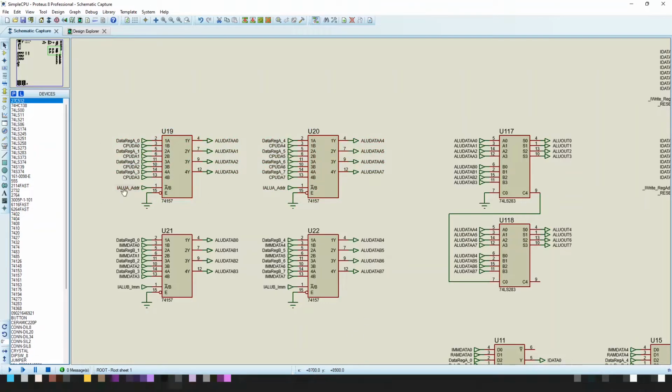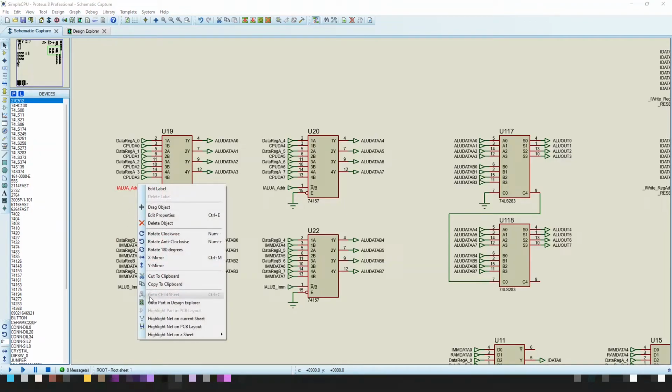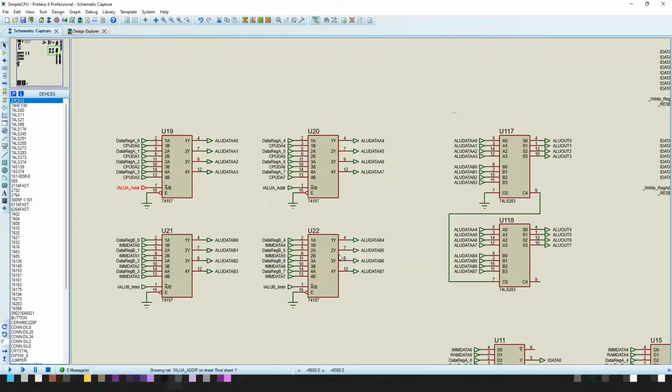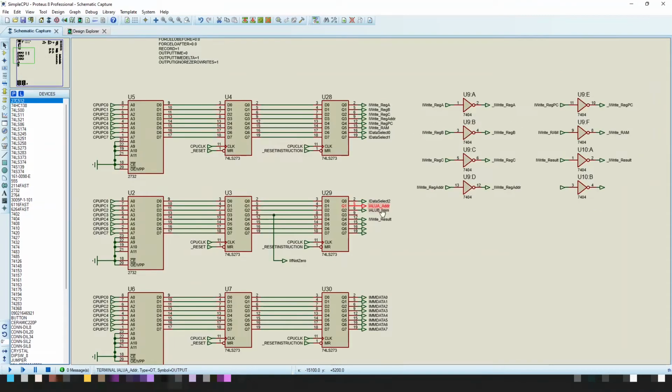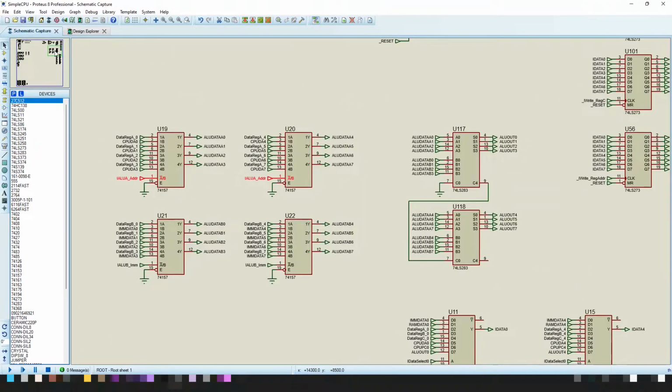So here what we have is the selector signal, and if I highlight that on the current sheet, then the selector signal comes back from the program ROMs as you would normally expect. Okay, highlighted here in red. The output signal here either selects on low A or high it selects B. And what we have is the input for register A or the input for the address register.